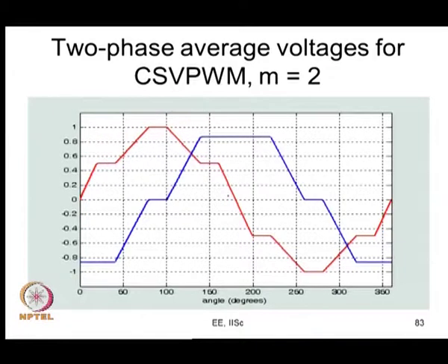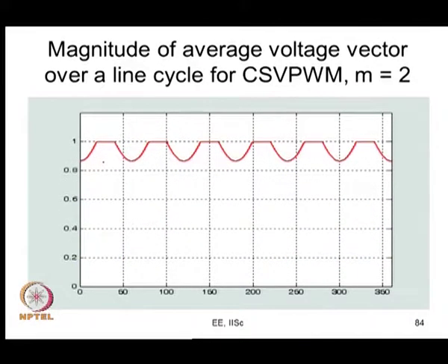So, you get these waveforms like this, and you will see here V alpha is equal to 1, V beta is equal to 0. So, this is a vector, voltage vector 1 is applied here, and here voltage vector 2 is applied, here voltage vector 3 is applied, here voltage vector 4 is applied, here voltage vector 5 is applied throughout. What happens is gradually this expands, the time for which this expands goes on increasing. Finally, only the active vectors are applied, V1 applied for 60 degrees, V2 applied for 60 degrees, V3 applied for 60, V4 and V5, and finally V6 is applied. That is what will be your 6 step mode. So, we are a little ahead of 6 step mode.